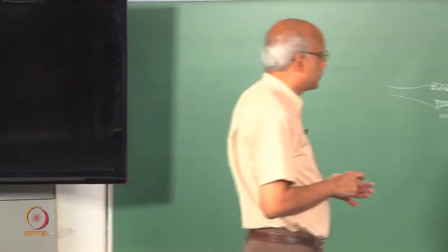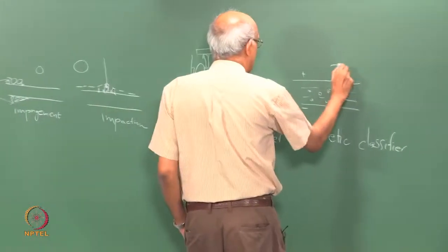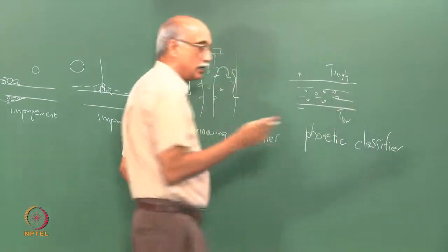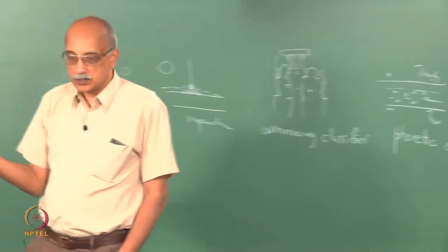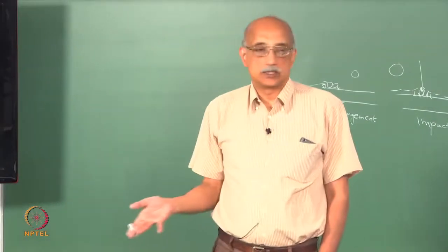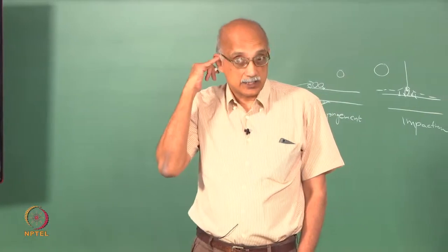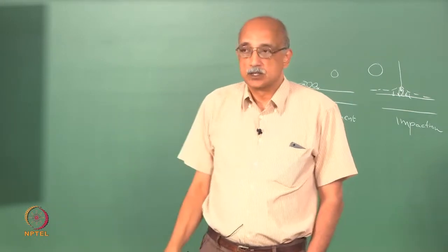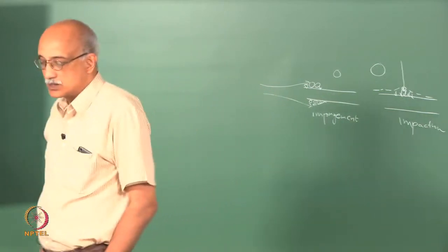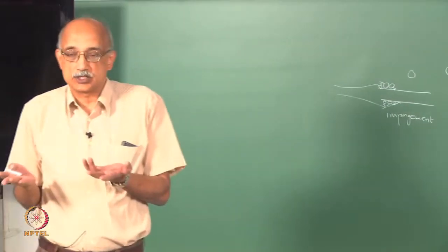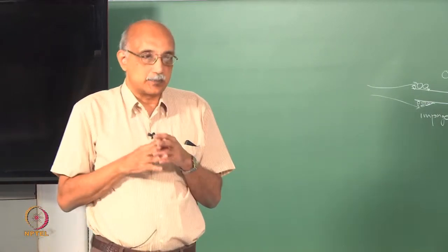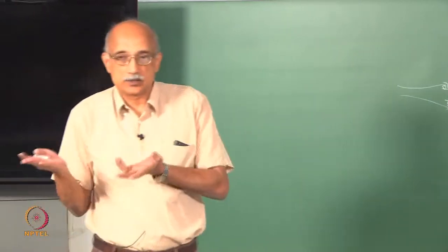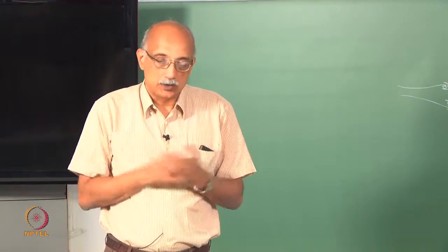So, here again if you have a T high here and a T low, particles that are heavier than the gas that they are entrained in will go towards the low temperature plate, whereas particles that are lighter than the gas will head towards the hot plate. So, you get in a sense not only collection but also classification. You are kind of simultaneously separating the larger particles from the smaller particles, or let us say the heavier particles from the lighter particles as part of your collection process.